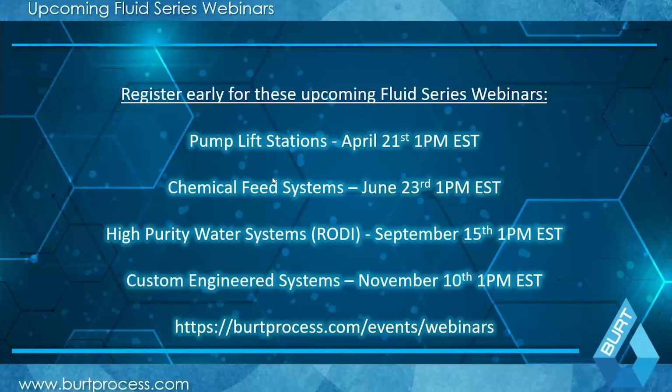you actually basically modulate CO2 gas, which will then pass up through your mixer backwash, and then obviously fade into the atmosphere above the tank. It's a little bit different sizing for those types of systems, as you have to utilize both the tank height as well as some different porosity of CO2 gas in those cases for treatment. But you certainly can use CO2 gas. It's a fairly common thing that goes on in the food and beverage industry.